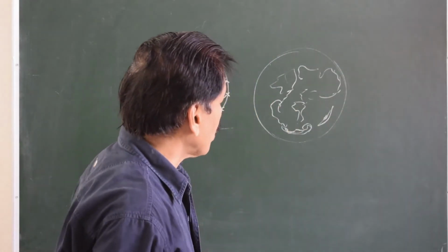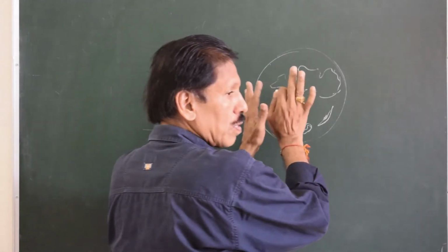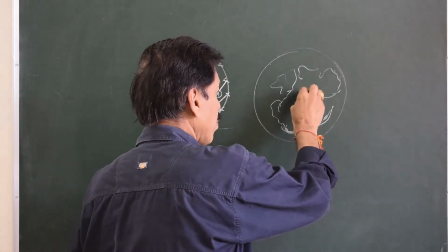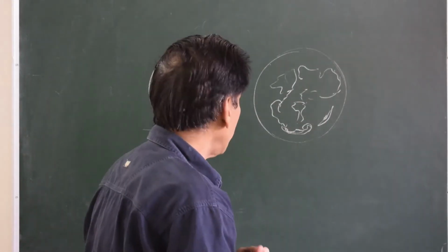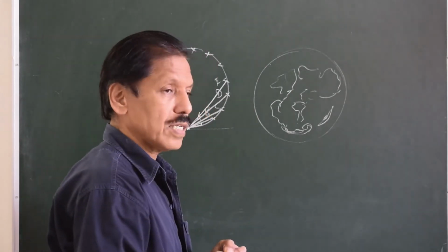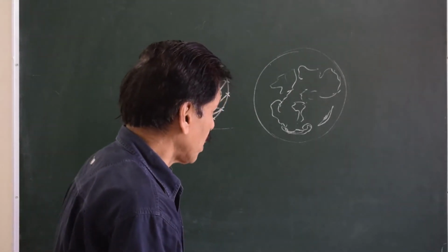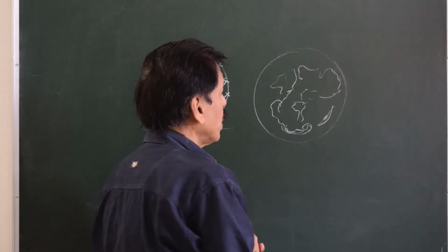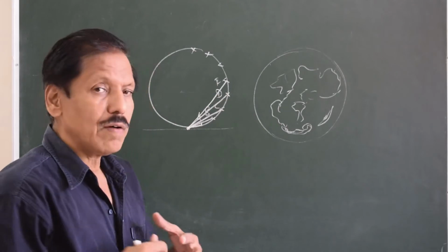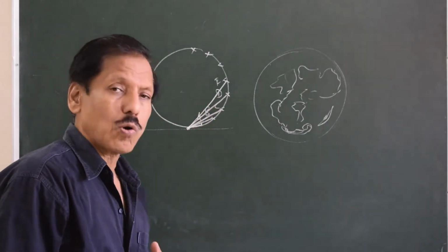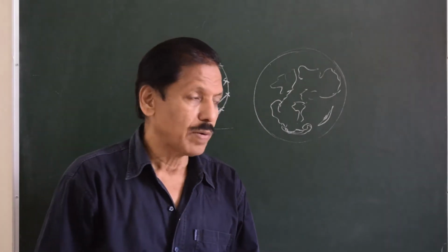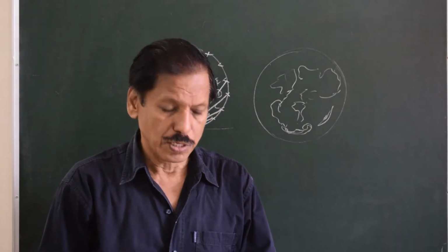So in this projection, you are not seeing 50% of the globe, you are seeing the entire globe. Whatever is the three-dimensional distance in space, not the great circle distance along the surface of the earth, the actual through and through distance to a point is represented. So in a way we have converted the three-dimensional globe into a two-dimensional disk. So that is Lambert's equal area zenithal projection.